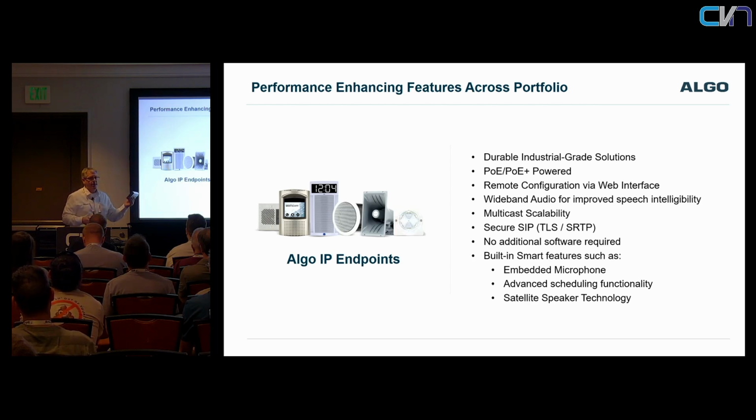And this is not an ATA, right? This is basically a SIP device that's providing a balanced line, 600 ohm output. It emulates a page port off of an old key system or a PBX. Again, high-end quality. Everything we build is PoE powered, so there's no local power required.